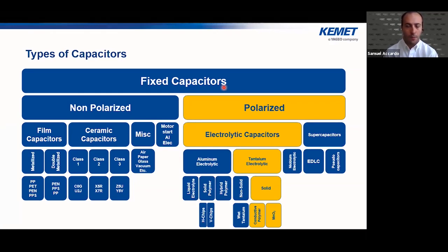I know a lot of people are probably thinking, well, isn't tantalum not electrolytic? Isn't aluminum electrolytic? Well, the answer is both of them are technically electrolytic capacitors. At KEMET, we offer solid tantalum capacitors. So there's solid, there's non-solid. Non-solid is wet tantalum, while the solid is conductive polymer and manganese dioxide, or MnO2. Today we're going to be talking about the conductive polymer and the MnO2.